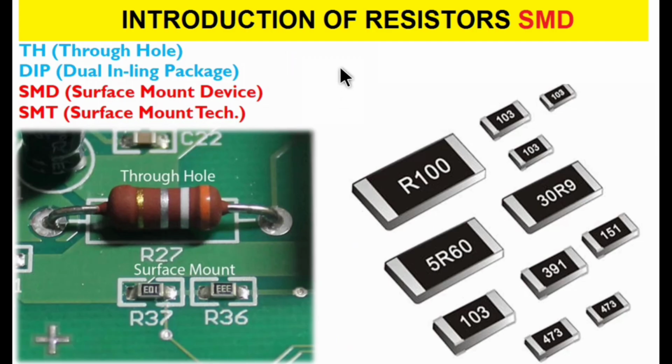Now I want to explain SMD resistors. SMD stands for surface mount device. That is the resistors that are soldered on the surface. The DIP resistors have 2 legs that go inside the board. But the SMDs are soldered on the PCBs themselves. Sometimes they call it different names. There are different types of SMD resistors, whose powers and sizes I will explain below.